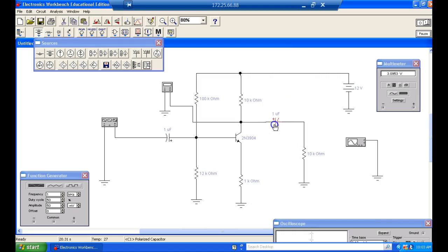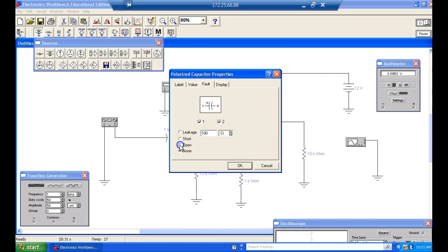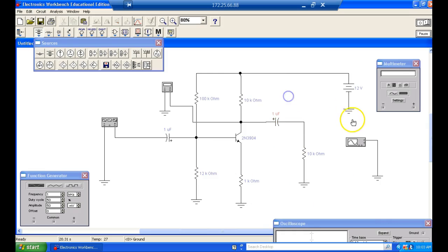What would happen if it opens? What would happen to my bias voltage? Everything, yeah, bias is going to be perfect. This amplifier will be fine, right? But what we would do is I'll come over here and measure this guy. Just measure right where we want it to measure, right? To understand. Of course, if that's measuring okay, then I have no need to even go over there, because there's no way this guy's going to be right and this guy over here be wrong, right? You understand that?